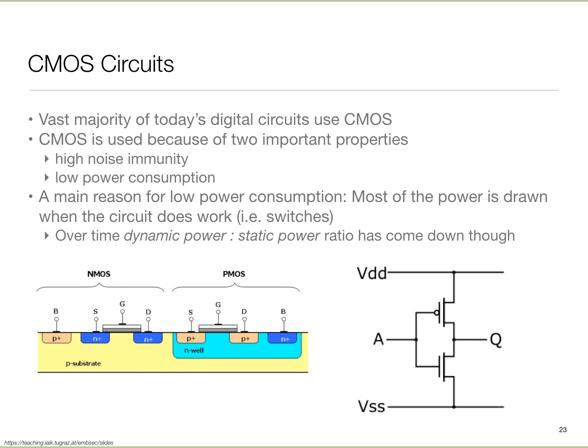So what happens in this case? Well, the reason we have low power is because these switches are complementary, so at no point in time are both simultaneously on. Well, not quite true, because when my input changes, the switches have to change their state, so there will be a tiny amount of time in which the top switch is turning on, let's say, and the bottom switch is turning off, or vice versa, and so some current will flow. But in a stable state, no current flows, or almost no current flows. In reality, again, these are non-ideal switches, so they leak a little bit of current.